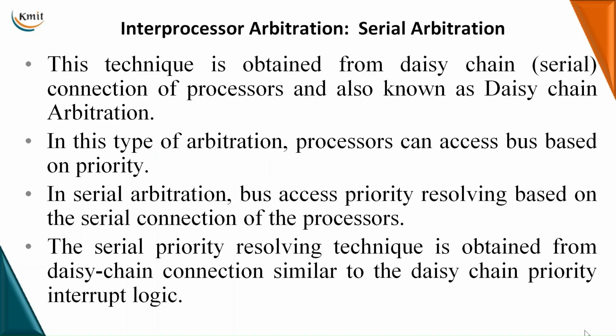In this type of arbitration, the processors can access the bus based on the priorities assigned to them. In serial arbitration, the bus access priority resolving is based on the serial connection of the processors, obtained from the daisy chaining connection similar to daisy chaining priority.